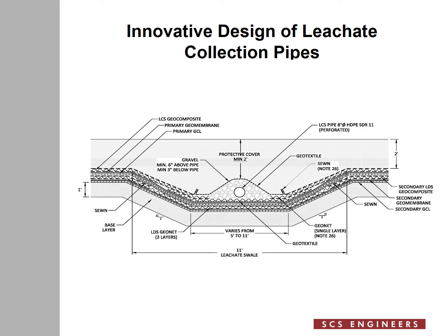Gravel has higher transmissivity than the geonet, and there's no geotextile between the geonet and the gravel to not follow that rule and to potentially cause clogging. Now in the next slide I'm going to take you through every step of the flow of leachate in reference to this innovative design for you to see the details, how every component of it meets the rule of transmissivities.